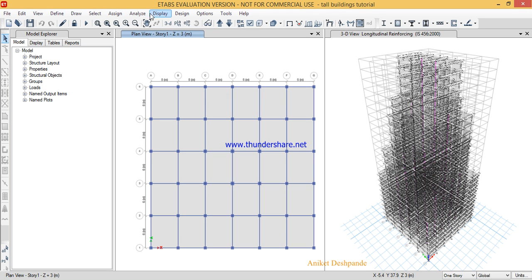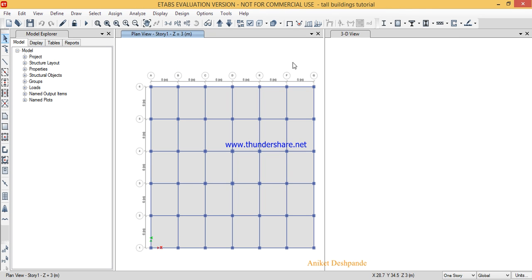So now this was about designing the model when three load conditions, that is the dead load, the live load, and the seismic load, are all acting together. Now we will look at analyzing the structure only when the seismic load is acting. Once we unlock the model, the analysis results of the model get deleted. So once again we are supposed to run the analysis.